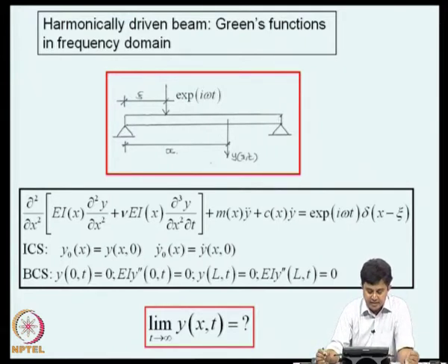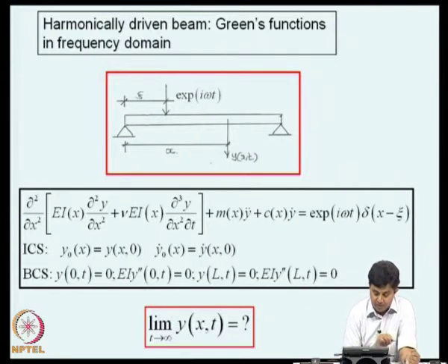We are eventually interested in analyzing the response of the beam to random excitations. So, to prepare the basic formulations to achieve that, we need to consider a few deterministic problems. One is the problem of a harmonically driven beam. We consider this beam, the boundary condition here is shown to be hinged at the two ends. The beam is hinged at the two ends, but this is just for illustration, it can be any other boundary condition as well.